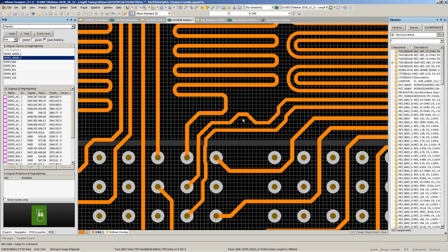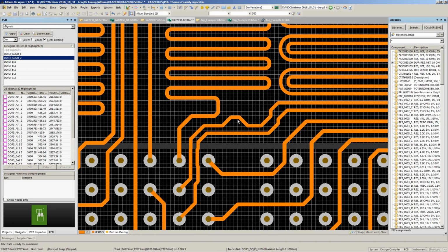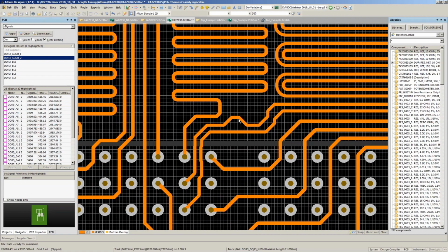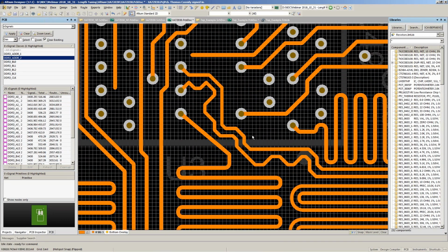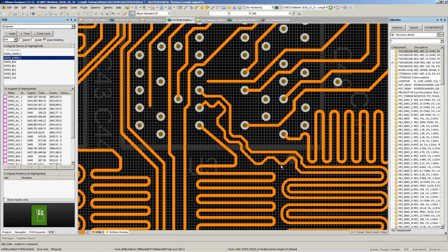Sometimes you're going to have a lot more impedance mismatch, but your signals will arrive at the same time. Also up here, since it was basically a C shape, I had to add a lot of length to the inner trace. So you can sometimes end up with some pretty weird stuff that doesn't really look like a differential pair, but you've got to do what you've got to do.